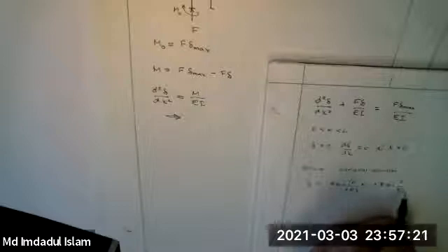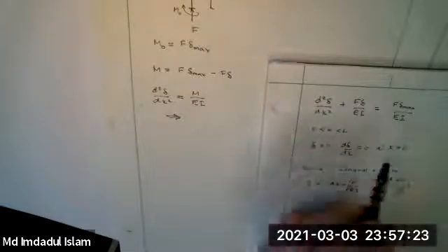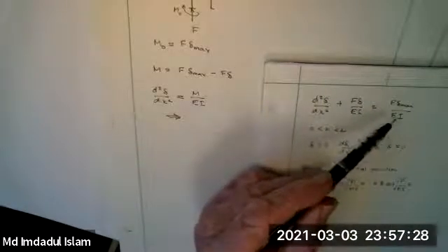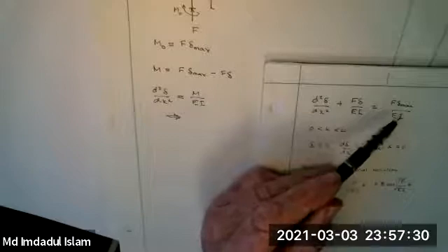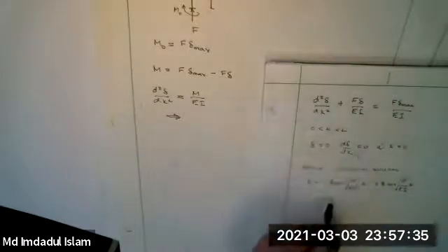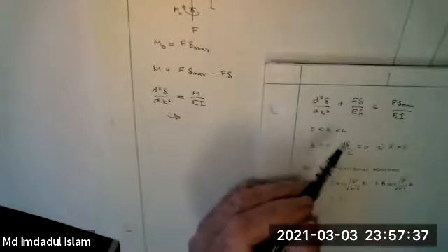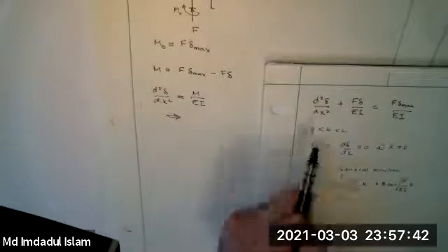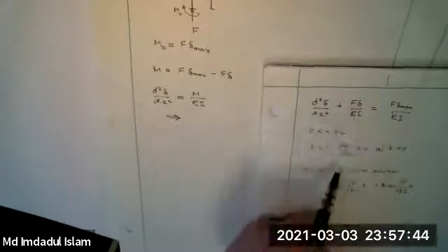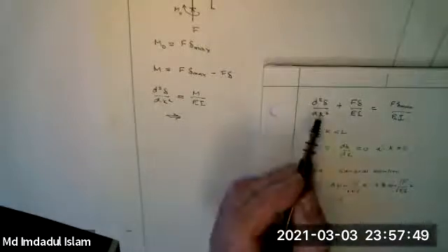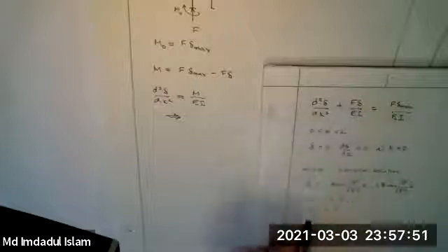Now this is not 0 here. So in your calculus class, to solve for this, you have a thing called a particular integral. And the way to do this here, this is just a constant, so I'll just take c, a further constant. When I substitute this in here, I differentiate these twice and add them to this, that'll cancel, but the c, I differentiate twice, can be nothing, but the c will go in here. So c equals delta max.